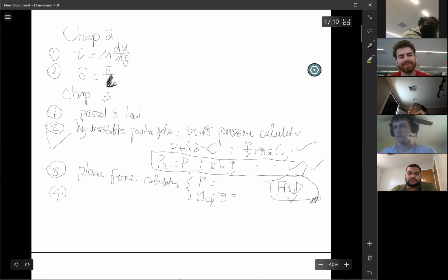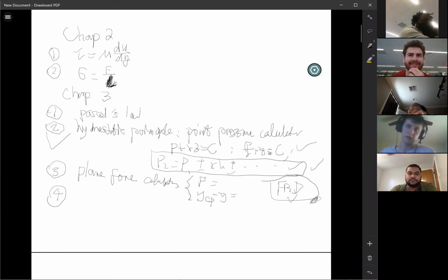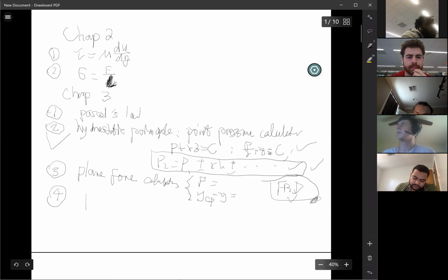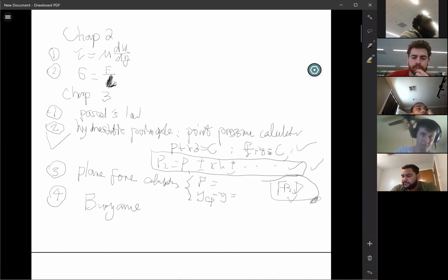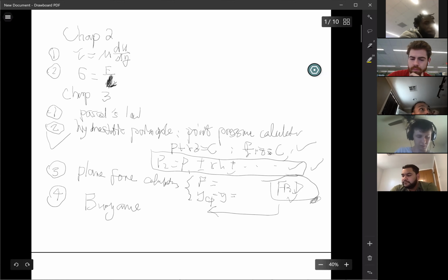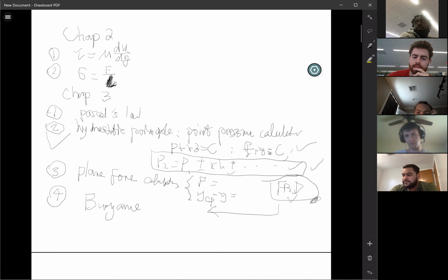What's the number 4 knowledge content you need in chapter 3? Buoyancy. Buoyancy could be a typical static problem. FBD, again, free body diagram. Write it down. Put the buoyancy always upward, as an arrow. Place all the possible forces in the problem, then write down the force balance. Sometimes you need a moment balance.